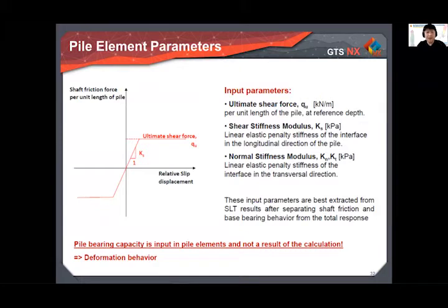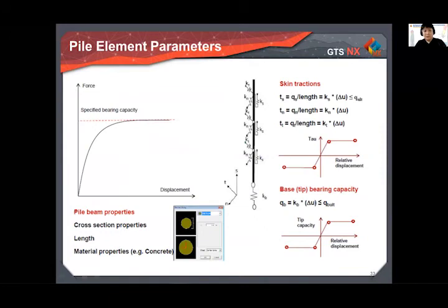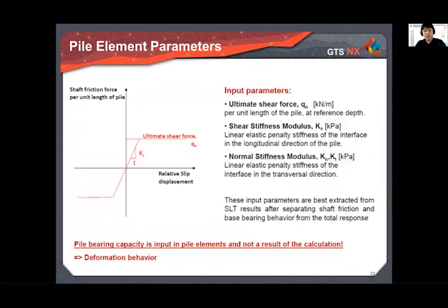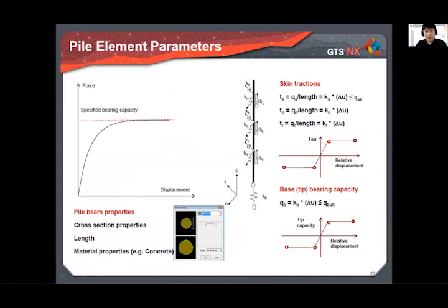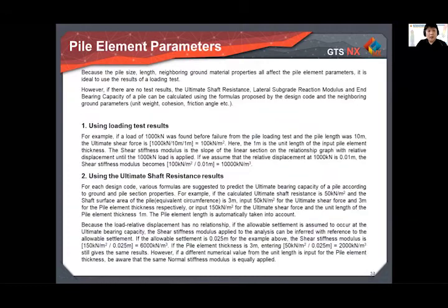So pile bearing capacity is input in pile elements and is not a result of the calculation in the FEM software. The purpose of using the piled raft foundation analysis in geotechnical software is to check the deformation behavior due to the superstructure, including the building or bridge. Again, this shows the schematic image of the pile element and interface element with the pile tip.